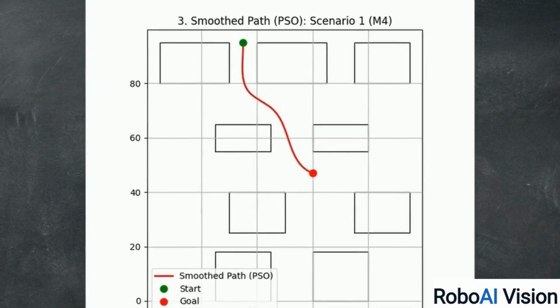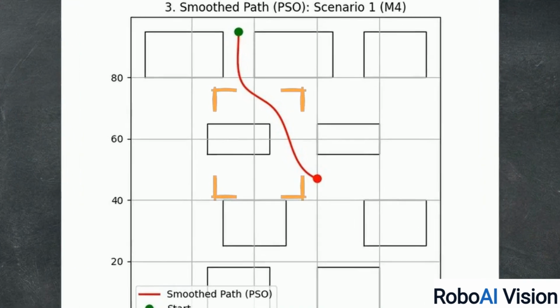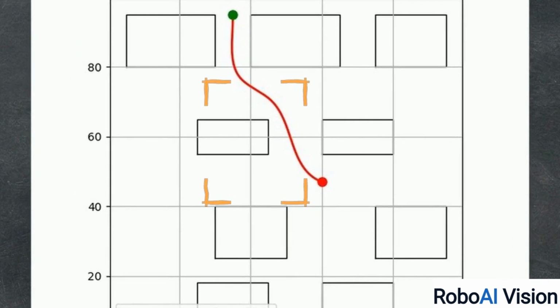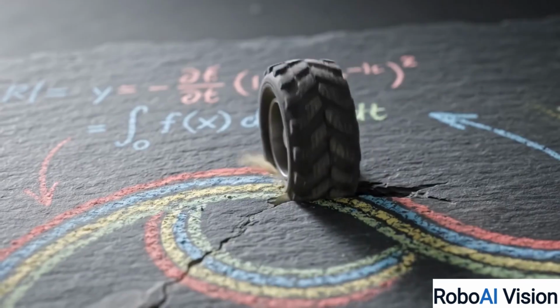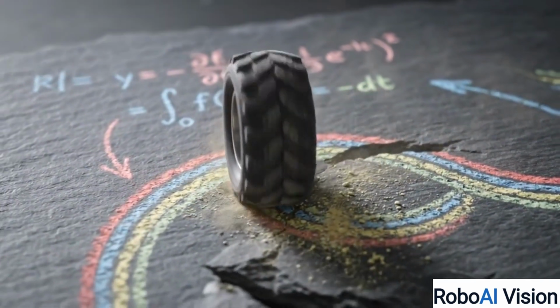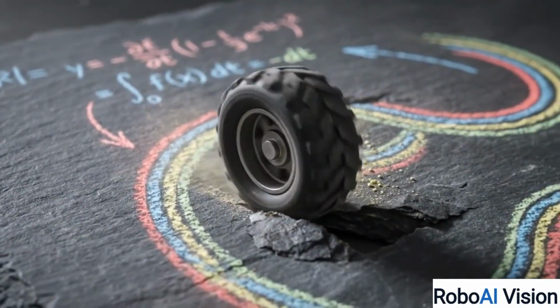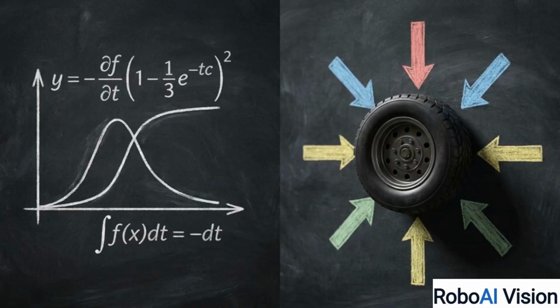Looking at the smoothed path in this chart, the dynamic forces change completely. Centripetal force is calculated as mass times velocity squared, multiplied by curvature. Because the B-spline turns the sharp corner into a sweeping arc, the robot can maintain a steady forward velocity. By calculating maximum safe curvature, the system explicitly caps the required centripetal force, preventing the tires from exceeding their physical traction limits. Geometric path smoothing is a direct method of bounding physical kinetic energy.